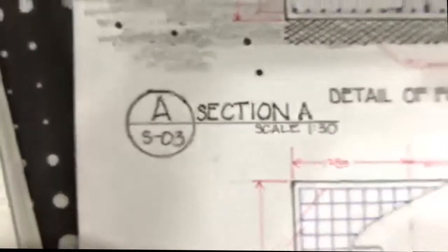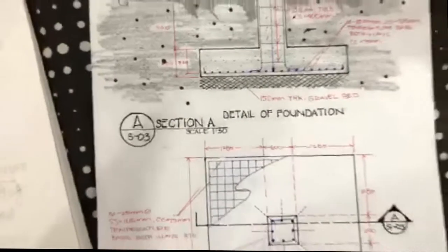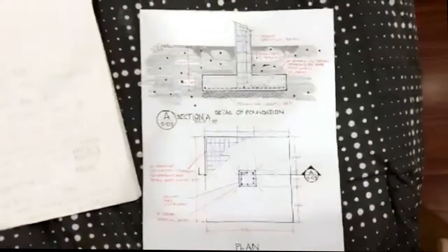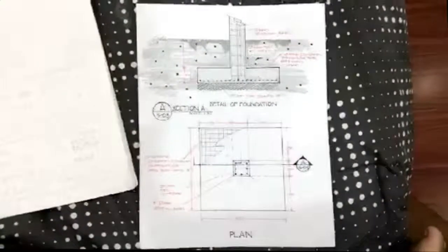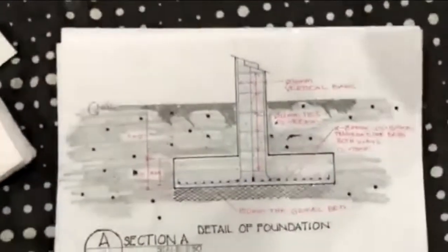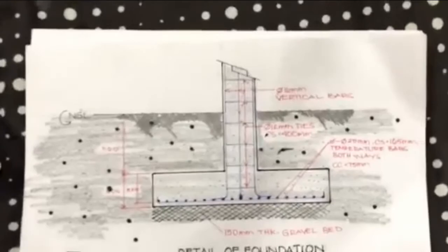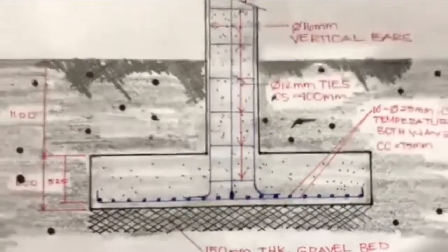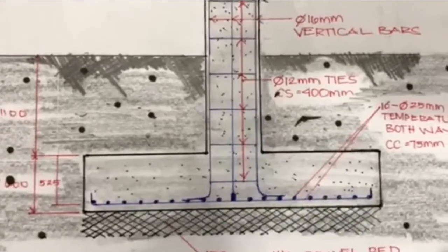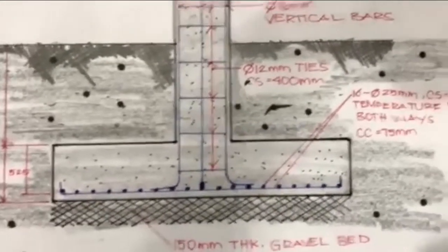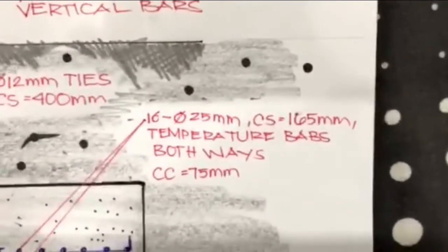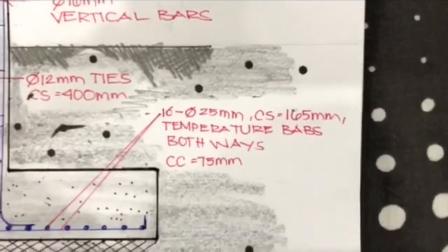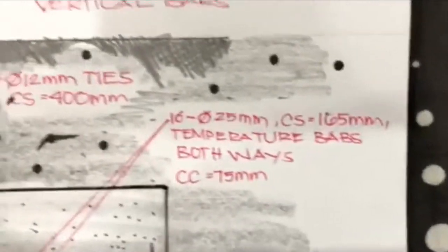After checking the adequacy of the depth and knowing the number of flexure bars of the footing, you can already show and draw the details. In detailing the front view of the footing, how the flexure bars will be shown in the actual footing should be drawn here. Also, the diameter, clear spacing, and concrete cover of the flexure bars should be detailed.